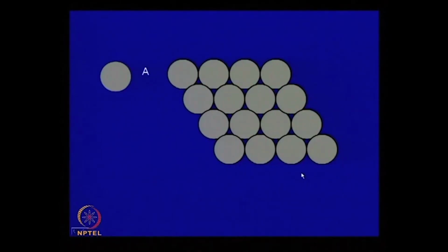Now, let us look at the way the atoms are arranged, and depending on that arrangement of atoms, whether there are any other types of dislocation that we can think of. So far the dislocation that we have considered is something like this. This is a close packed plane of a face centered cubic crystal. All these atoms are closely packed, this is a 1 1 1 plane, and these directions are 1 1 0 directions, the face diagonal directions.